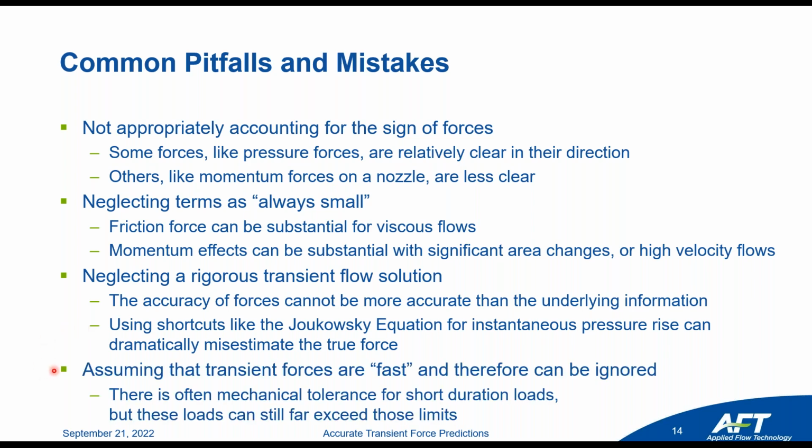And another thing that we've seen is people may be cognizant of all of these things and they say, yes, I know there's a huge force, 10,000 pound force, but these transient forces are fast. Those waves are moving near the liquid speed of sound, so that elbow pair might only be loaded for a few milliseconds. And we have seen people say that we can ignore that because it's not a static load.